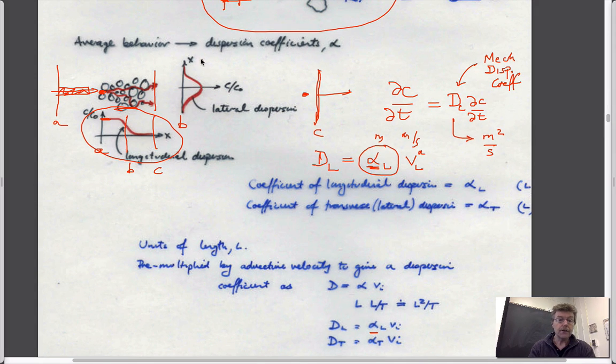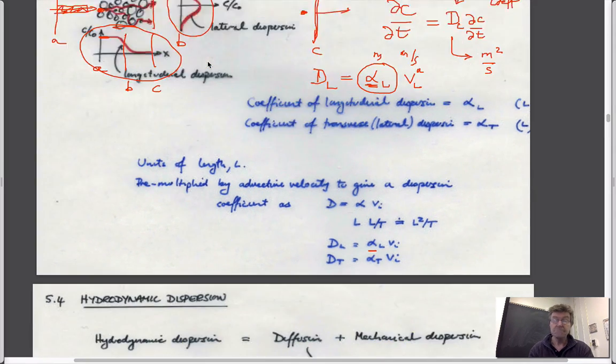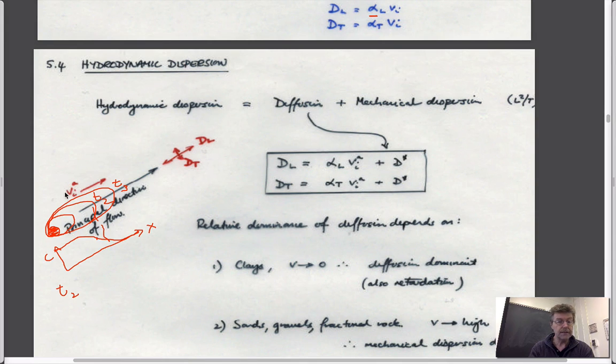If you look at going across this plume, then you'd expect if you drew a section across here, then that section would look something like this at time t2. Concentration, I guess this would be the y direction. And so it seems that when we write this equation that represents the behavior of what's going downstream, the advection-diffusion equation we should write should be something like this.